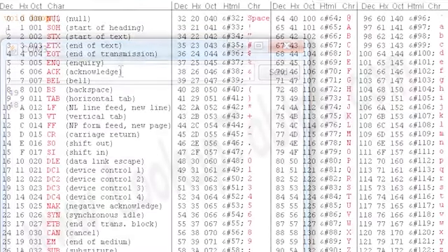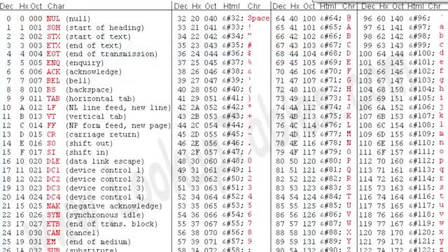Okay, let's look into why we're not getting the same numbers back that we send it. The answer to our problem lies in data types. If you go to Google and look up an ASCII table, you'll find something like this. It breaks down the different data types and how they relate to each other. We're sending a character, a char, of 0 or 1, and you'll notice the decimal representation of 0 or 1 is 48 and 49, exactly the numbers that we were getting.